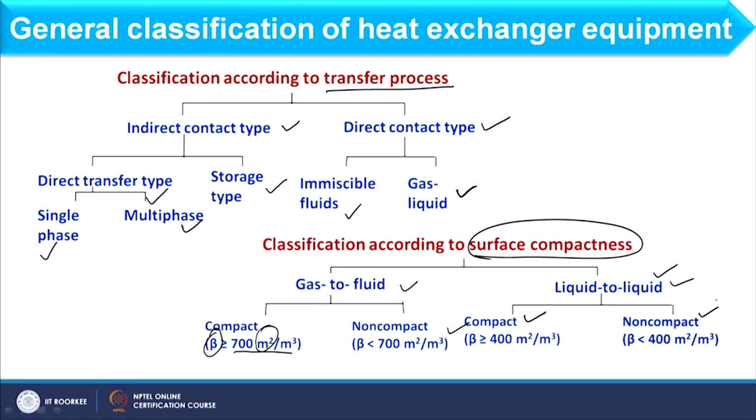Now, what is the application of these compact exchangers? As you have already understood, in a small volume we have to increase the heat transfer. How do we increase it? We increase the heat transfer by putting fins. Secondly, because its size is very small, its utility should be where size really matters, for example aerospace.